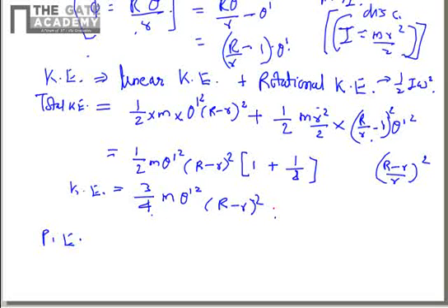What is the potential energy? The potential energy in this system is due to the gravitational potential energy. So you have the cylinder sitting at the equilibrium position. This is a deflected position, and the center has moved to some height, this h, due to the angular displacement theta about the center of the cylindrical surface. This is theta. So what is this height h?